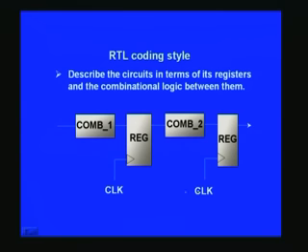You have a combinational circuit, and it can be any complex combinational circuit, and then follow this with a register, registering this combinational output, and this may be an intermediate output, and then follow the same pattern successively, and this keeps going in this fashion, and data flows in this fashion naturally.